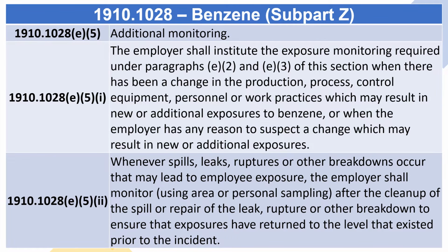exposures. Whenever spills, leaks, ruptures, or other breakdowns occur that may lead to employee exposure, the employer shall monitor, using area or personal sampling, after the cleanup of the spill or repair of the leak, rupture, or other breakdown to ensure that exposures have returned to the level that existed prior to the incident.